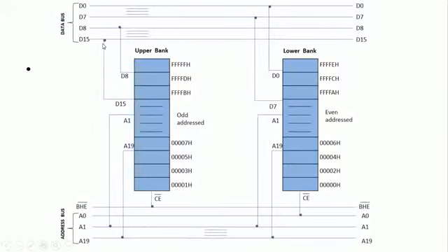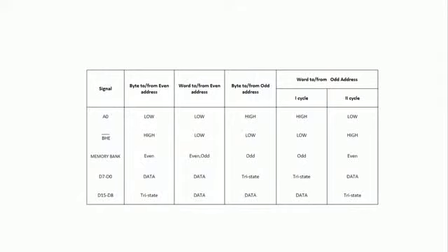If you want to realize this, generally if you take a 16-bit number, it has a lower byte and a higher byte. The lower byte should be transferred by the lower order data bus, and the higher byte by the higher order data bus, because the data bus is 16 bits wide. But if you are not giving the even bank address as the offset address, there is no confusion actually, but the microprocessor takes two bus cycles instead of one bus cycle.